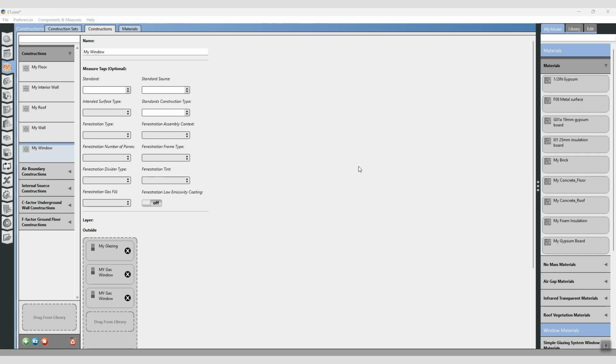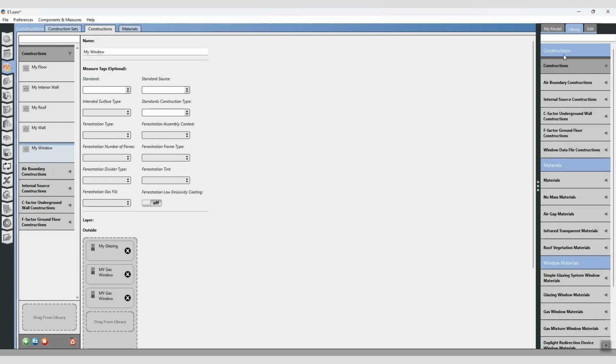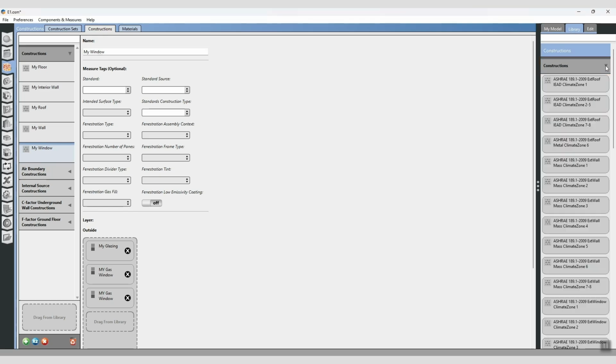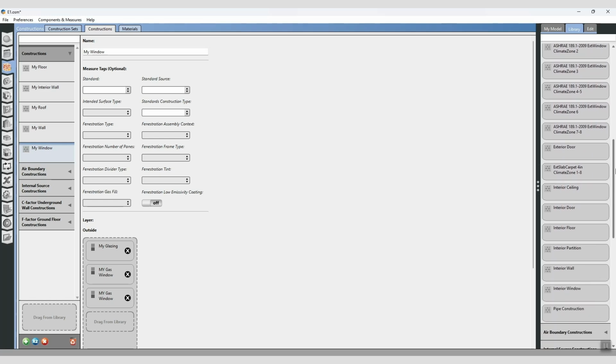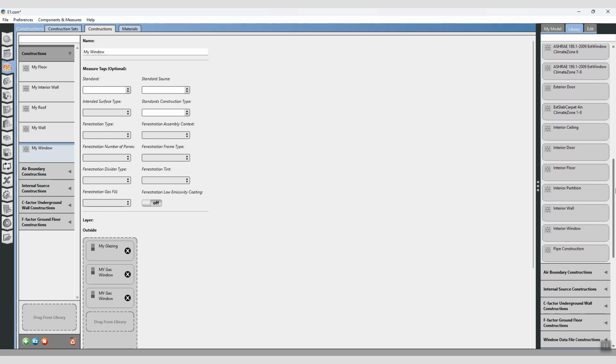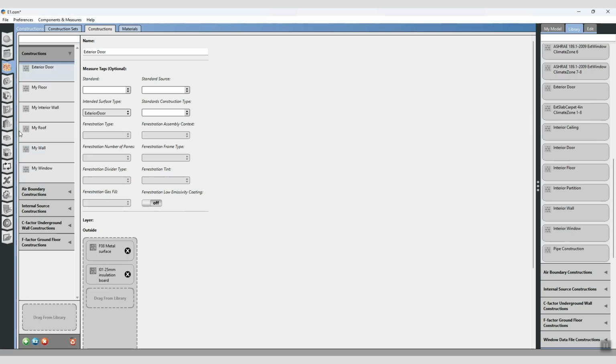Libraries in OpenStudio aren't just for materials, they can also include complete constructions. In the OpenStudio application, head to the Library section and select the Constructions category to see any pre-built constructions imported from an OpenStudio model file or the Building Component library. Just like with materials, you can drag and drop these ready-made constructions directly into your working model. The best part? This automatically brings along all the associated materials from the library, saving you effort and reducing the chance of mistakes.